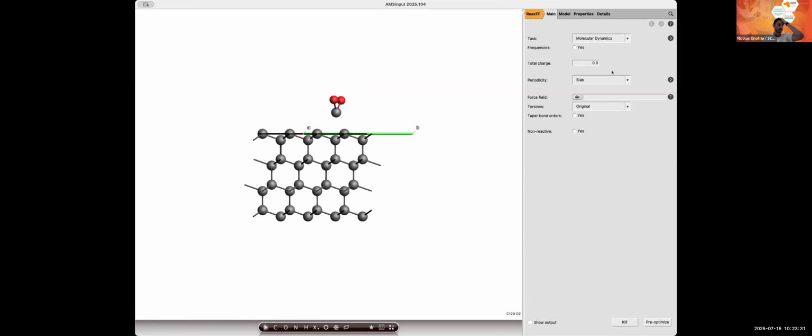So I don't go over the model because I know yesterday you talked about it. It's just a many-body potential. The nice thing we have is there is a library of ReaxFF force fields that you can just find. When you select this engine, you see the force field here. We have about 100 of those force fields because the interaction is parameterized over a finite set of elements, right? It's not a universal model.